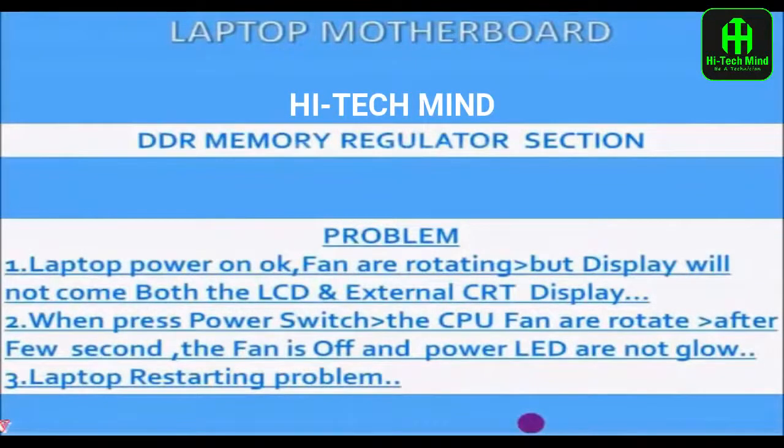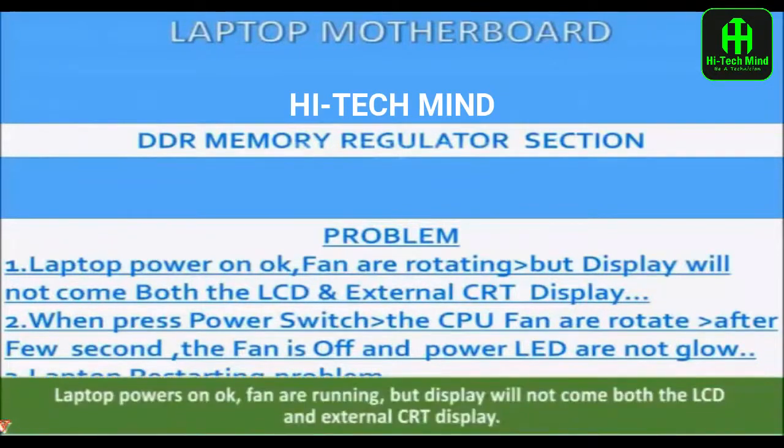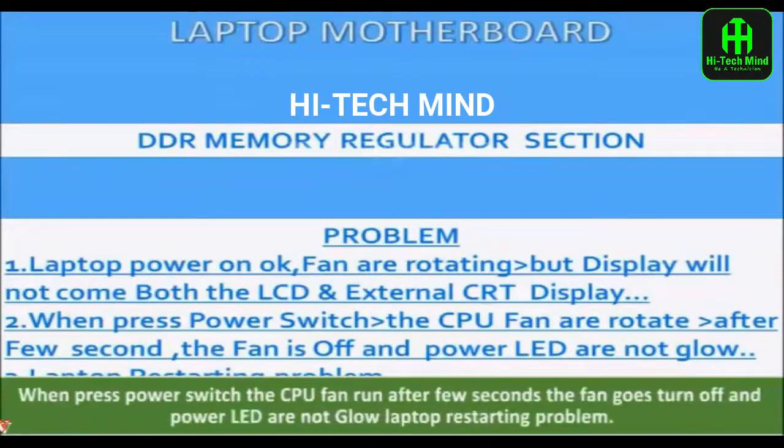In the DDR memory regulator section, we are going to see about the problem faced on laptop power on. The fan is running, but the display will not come, both on the LCD and external CRT. When the power switch is pressed, the CPU fan runs, and after a few seconds the fan turns off and the power LED does not glow. The laptop restarting will be the problem.